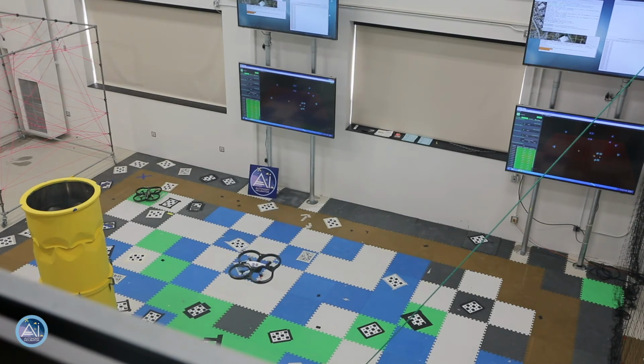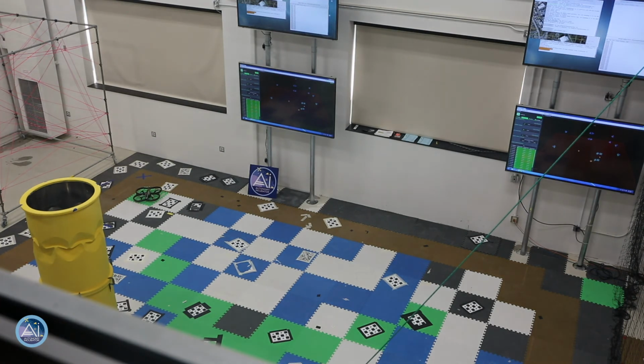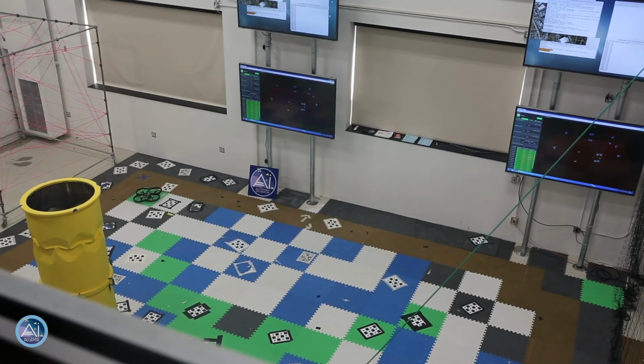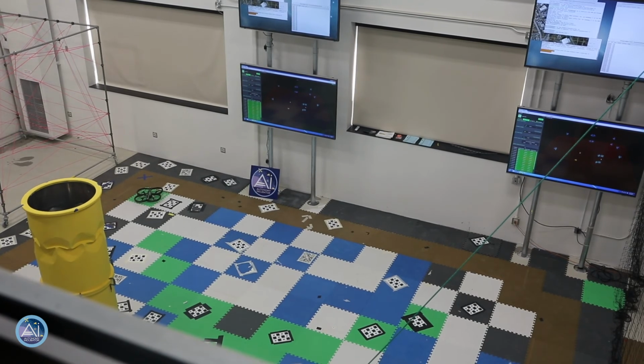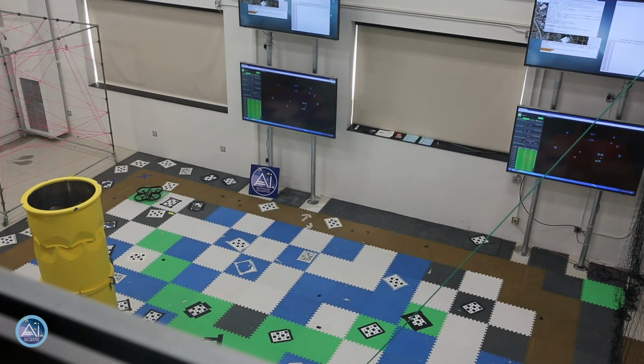So we're running both vision techniques. If you see on the monitor, on the left is the entire detection with a neural network. On the right is just the Sobel detection, showing the actual lines of damage. And so right now, the white drone is actually told to sit in a holding pattern because it's detected the second drone has connected. And so it's just going to keep flying those waypoints up top until it reaches the minimum required number of scans.